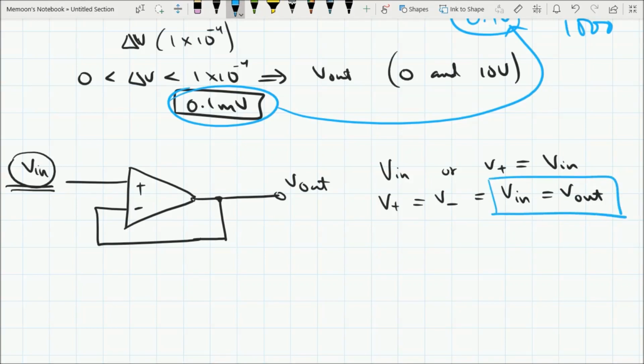We can see here, we have derived this relationship. The output voltage is equal to the input voltage without any gain. So this is a unity gain buffer. What is the purpose of that? We have reduced the very high gain of an amplifier to 1. It is no more amplifying. It is just giving a unity gain to the signal. So whatever signal we are sourcing at the input is traveling to the output without any gain. What's the purpose of this?